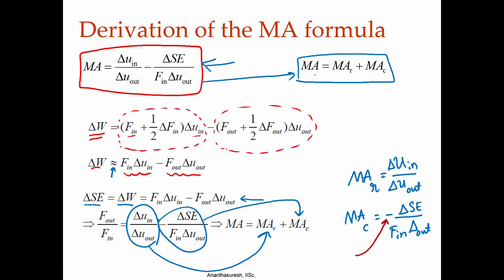So, the compliant mechanism's mechanical advantage is going to be always less than or equal to MAR, that is one observation Solomon and Midha made. That is actually clear because part of the input energy is stored in the compliant mechanism. So, both the efficiency and mechanical advantage will be hampered compared to the corresponding rigid body linkage if there is one.